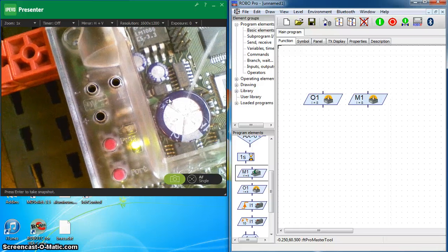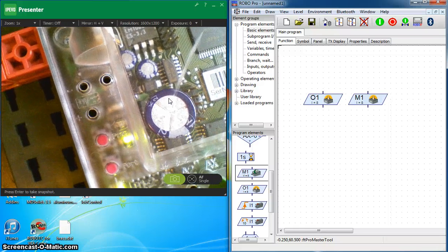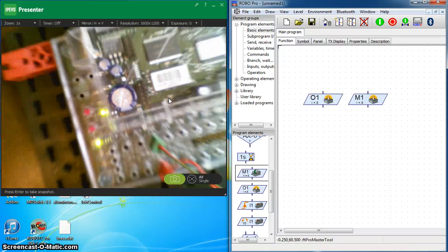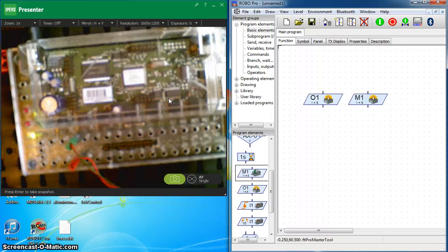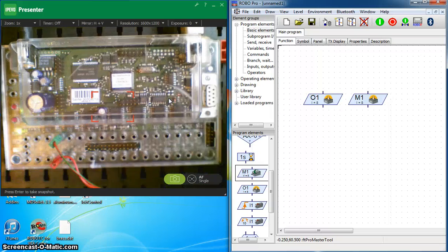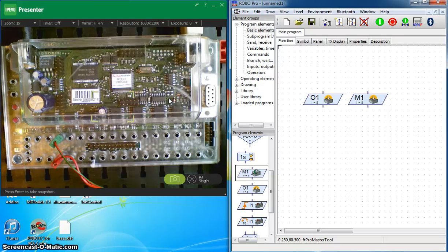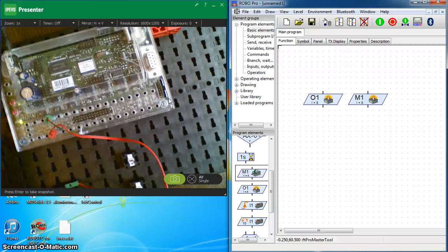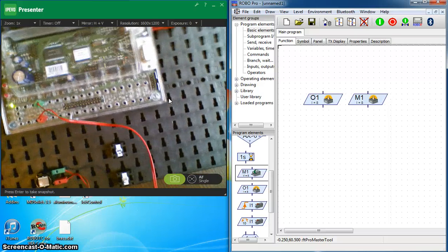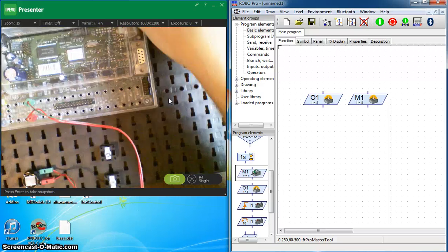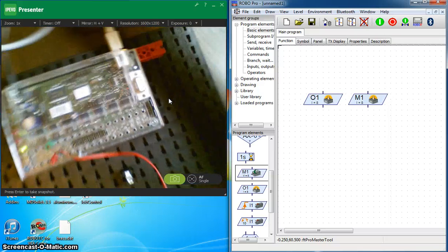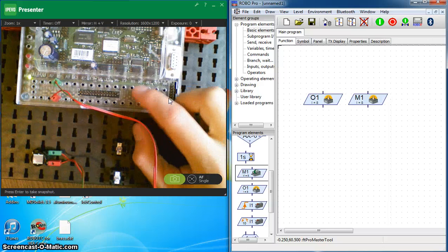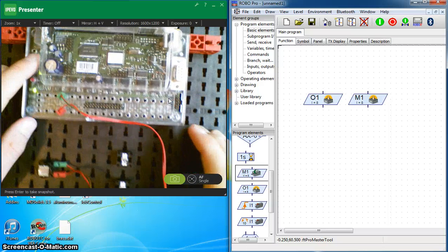It's in a little different location on the old intelligent interface, and there are multiple ground ports on the Robo TX interface, the little black interface that is the newest version. But I want to show you how to hook it up so that you can wire multiple lamps, not necessarily together. They'll have independent function, but you can put two lamps in one M1 slot using that common ground port.